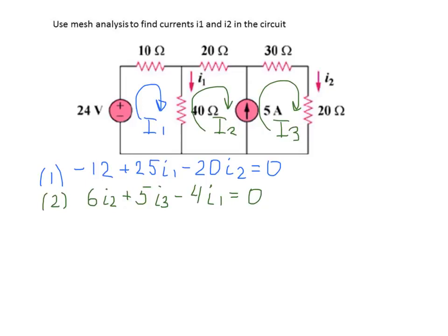How to do this? Let's look into the upper node, where the 5 amps is coming in. So I just draw this node larger. This is the node, with the current of 5 amps coming into the node. And what other two currents belong to this node? This is the current I2, which is also coming into the node, so we put the arrow in, and that will be current I2. And also there is the current I3 going out from the node. So it goes this way, current I3.